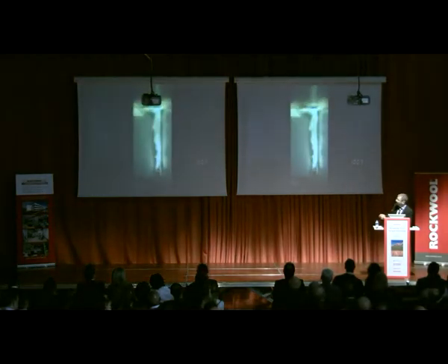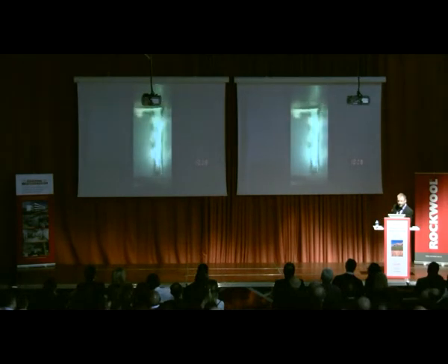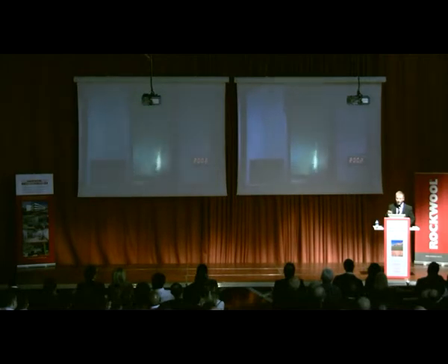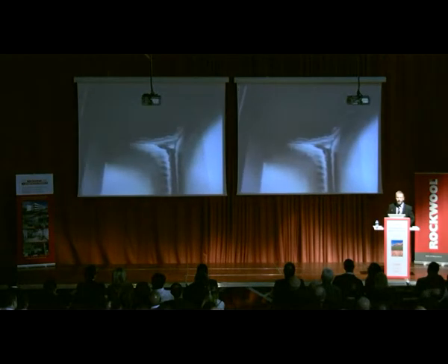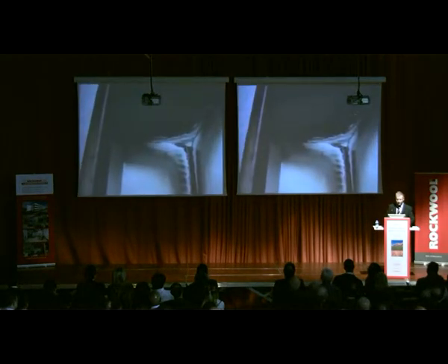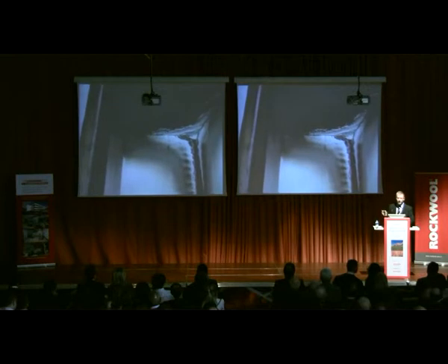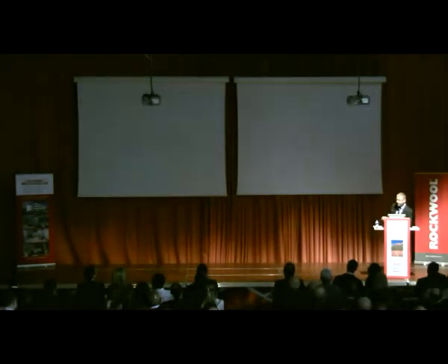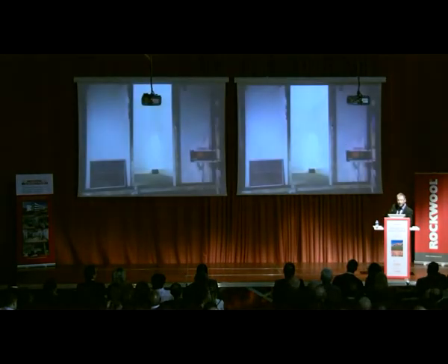Now you can see the flame gets bigger. After 10 minutes, it was increased 3 times in power. It starts to attack the ceiling of the room. And the test should continue until 20 minutes. So now we are at the end of the test. We can see some smoke coming from the glue between the panel and between the steel and the insulation, from the coating, from the paint, but there is really no big damage apart from this damage to the surface.